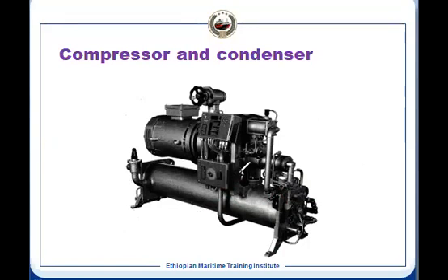And this type of compressor is the screw type compressor, because where large capacity is required, there we use the screw type compressor. For example, passenger vessels, even VLCC and ULCC, use this type of compressor because the capacity is very high, where the mass flow rate has to be high. Whereas the reciprocating compressor increases the pressure very high, but the mass flow rate is less. So for large capacity on cruise and passenger vessels, they use this type of screw compressor, because you need very, very large capacity, as there is hotel accommodation for the passengers. That has to be conditioned also.